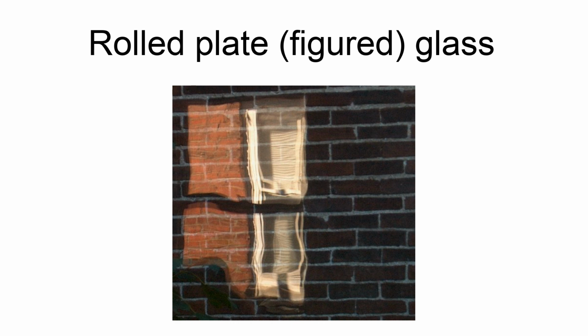Only some of the figured glasses may be toughened, dependent on the depth of the embossed pattern. Single-rolled figured glass, where the pattern is only imprinted into one surface, may be laminated to produce a safety glass.